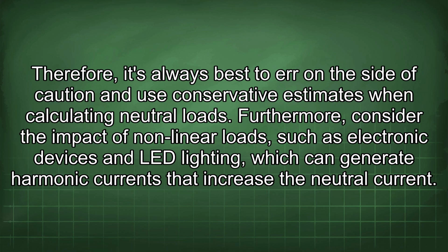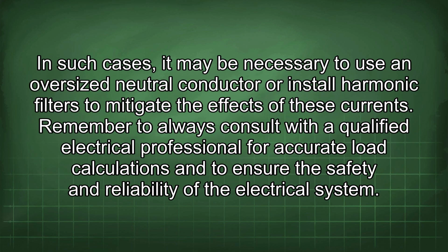Furthermore, consider the impact of nonlinear loads such as electronic devices and LED lighting, which can generate harmonic currents that increase the neutral current. In such cases, it may be necessary to use an oversized neutral conductor or install harmonic filters to mitigate the effects of these currents.